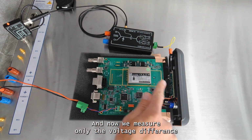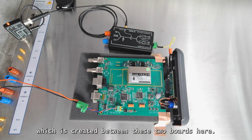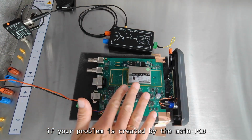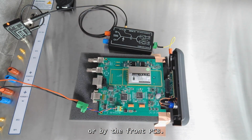And now we measure only the voltage difference which is created between these two ports. And so you can evaluate if your problem is created by the main PCB or if the problem is created by this connector or by the front PCB.